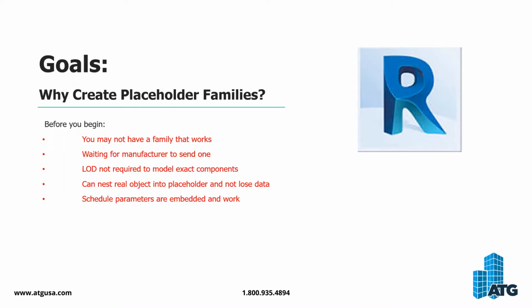When I think of a placeholder family, usually I want it to be very loose, easy to use, and a starting point for every family type that I want to build. I might make a couple of specialty placeholder families specifically for face-based objects if I need them. But in most cases, a placeholder family is going to be very generic, but also very parametric.